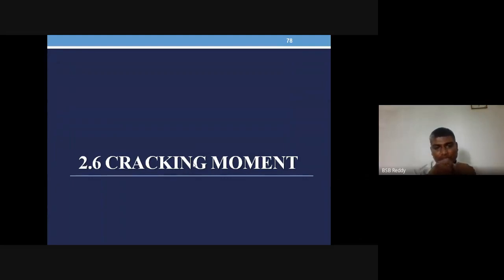Okay, so if you have a UDL, the uniformly distributed load, you should have force developed everywhere. The same resistance also should be distributed. So that's why a parabolic cable profile is suitable.